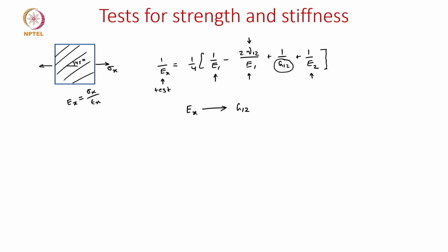But at the grippers, whether we allow this shear to occur or not will play a role on the measured loads. So if we look closely, there are some problems even with this test. People have come up with better tests, but bear in mind that testing a composite under shear is a challenge. There are tests which are now better, but each test has its own limitations.